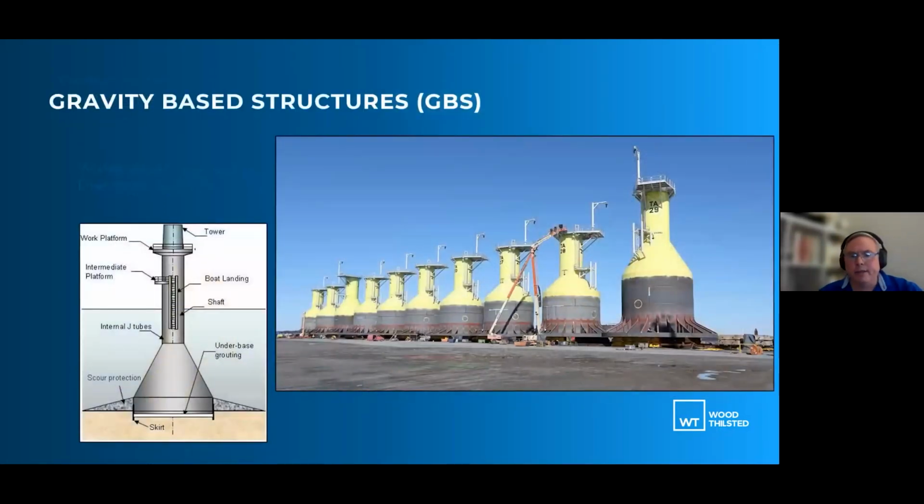I'll touch on this just briefly. Gravity bases, this is probably the smallest piece of the installed base at the moment. It is quite helpful in some locations for very specific reasons, where penetration, for example, might not simply work, but you've got a firm enough seafloor that you can set a large structure on top of it. These are also very expensive to build. They're basically made out of concrete, which means that there's a whole bunch of steel reinforcing inside the concrete that has to be wired together by somebody with little metal strips in his hand and a pair of wire cutters. So very time consuming, used only in very specific applications.